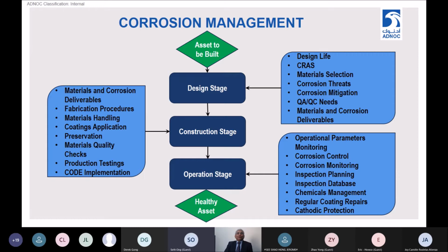Chemical management, undoubtedly a very important aspect, especially where you have carbon steel materials used primarily in oil and gas business, in the water injection systems, in the conveyance or transport of fluids through subsea and above ground pipelines, underground pipelines. We use a lot of carbon steel, which goes with chemical management and chemicals used for corrosion inhibition and corrosion control.